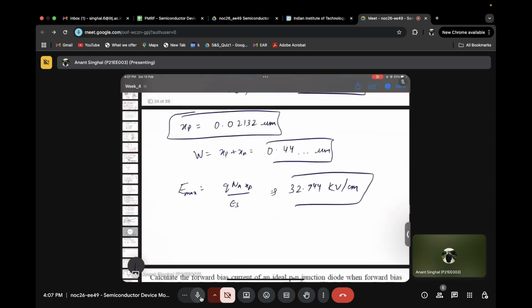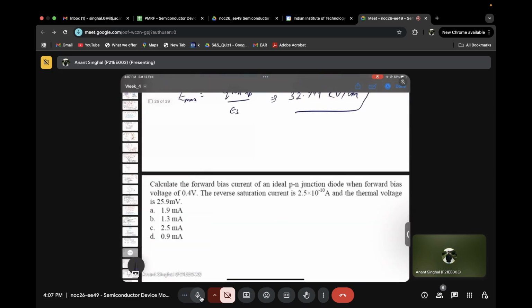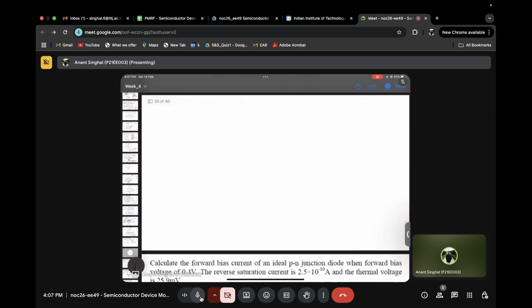Okay. So let's quickly do one more problem maybe. We still have some time. So let's do a very conceptual thing now. I'm taking an n plus n device. That means not a p-n junction but an n plus n junction. I'm giving you ND1, which stands for 10 to the 18 per centimeter cube, and ND2, which stands for 10 to the 15 per centimeter cube. And ni, for simplification, let's take 10 to the 10 per centimeter cube. Temperature is still 300 Kelvin.